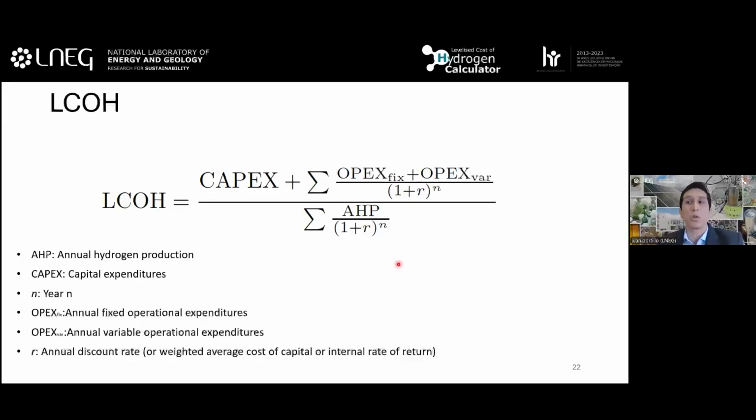And these costs should be also translated into a reference point. And there are artificial ways in order to include it. If you have questions regarding this, we can discuss it at the end. Okay. What is the unit output of this levelized cost of hydrogen? It is normally expressed in euros per kilogram of hydrogen, or euros per kilogram simply. This, as I said before, can be translated into euros per megawatt hours because the hydrogen has specific energy content, and we can make this conversion.